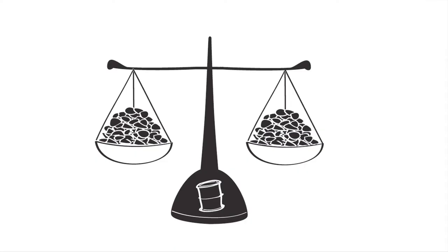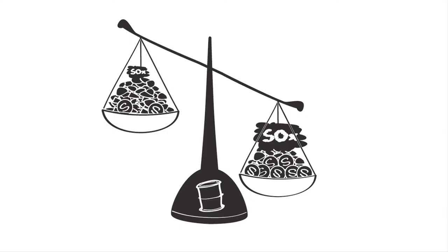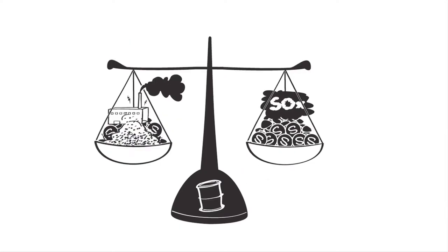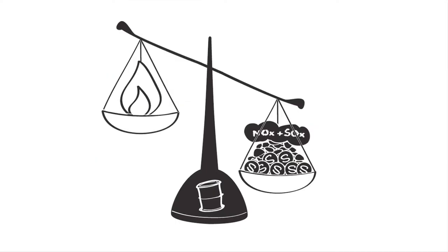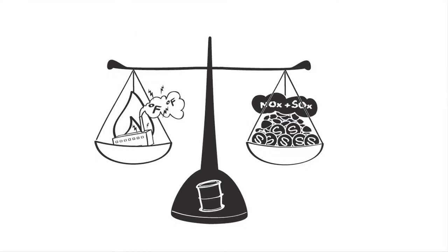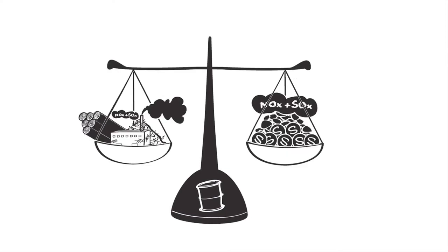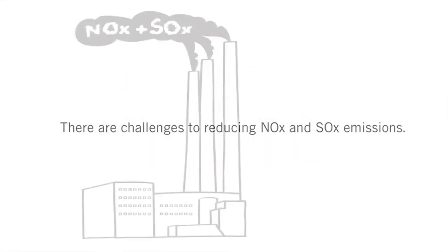Let's talk about fuel substitution co-benefits and trade-offs. Low sulfur coal lowers SOx emissions. However, it can affect boiler efficiency and other pollutant emissions, increase ash loading, and can lead to unsatisfactory performance of emissions control equipment. Natural gas, though cleaner burning, yields more water vapor and therefore contributes to greater heat loss out of the boiler stack. Biomass and wood lower SOx and NOx emissions, but their firing has been known to accelerate boiler component corrosion.